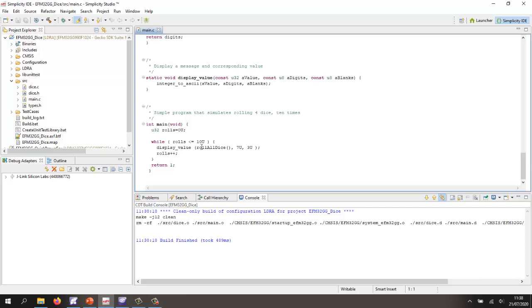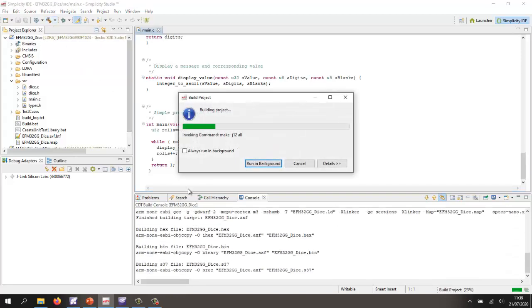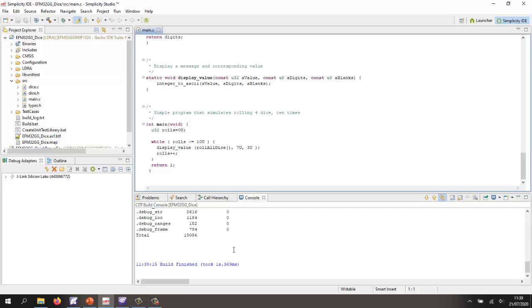And then I'd like to execute the code on the target, and as it executes, I'd like to find out, well, how much of this code have we actually exercised? I probably won't get 100%, and so then I'll use the unit testing tool tbrun in order to be able to complement that coverage and do some unit testing. Now, let's check first of all we can build this project. So there we can see that's successfully built.